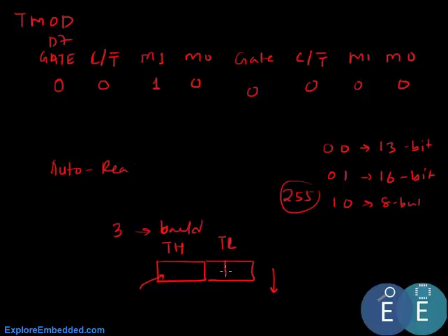That is very helpful because we want to generate a baud rate of 9600 to transmit each and every bit. We know from a previous discussion that if the counter ticks 3 times, then we generate a frequency of 9600.